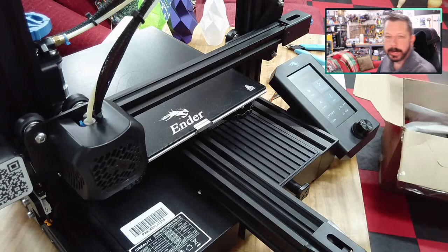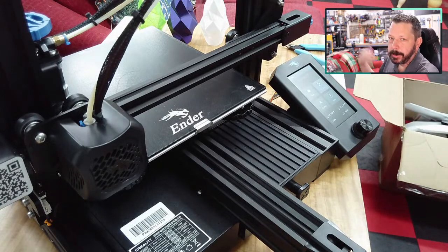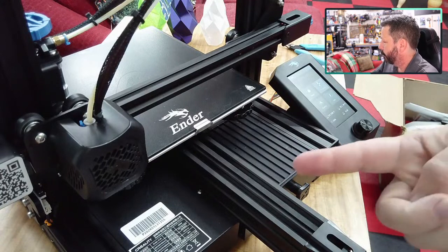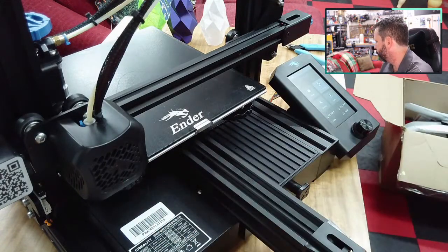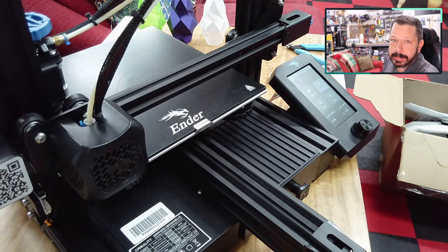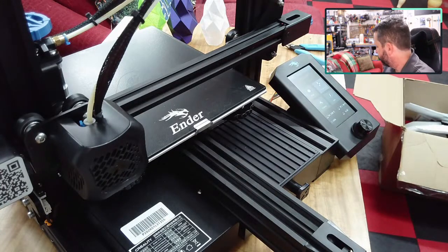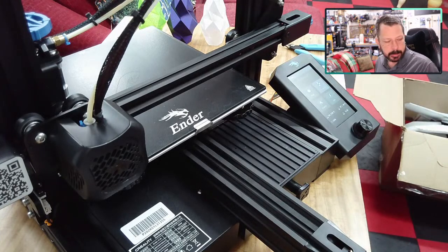So when I stopped the print, it had automatically started shutting down all the heaters, and so the hot end was down at 120. For PLA, it needs to really be at least 175 or higher, and normally I'm printing at 205, so it was below the temperature that it can actually extrude anything. So I need to let it heat back up before we can force filament out of there.